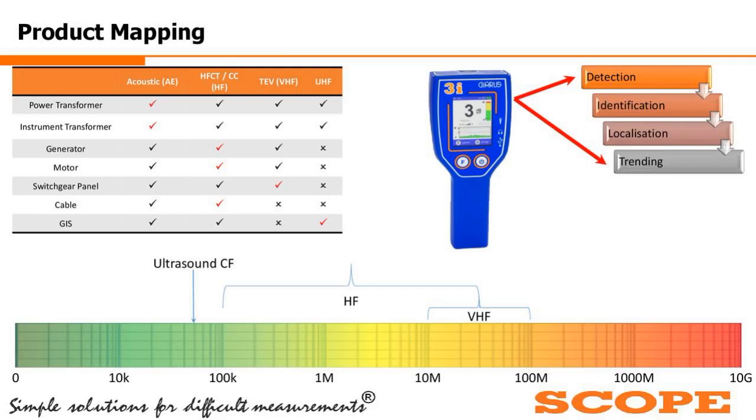So here we can detect the existence of the PD. How much PD, we can see on the LCD screen: what is the count, how much dB, or what is the severity, but no graphical analysis as shown in PRPD and other things is available.